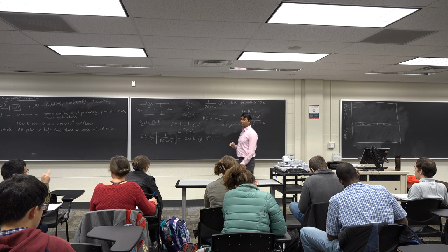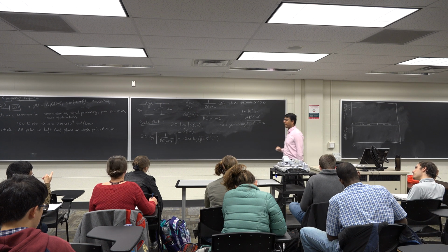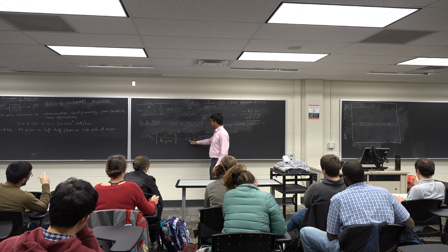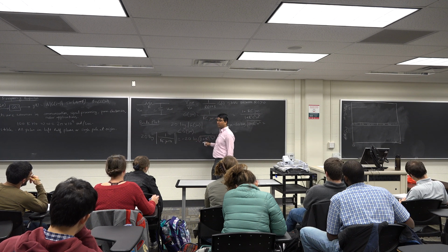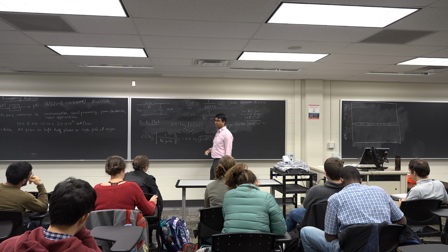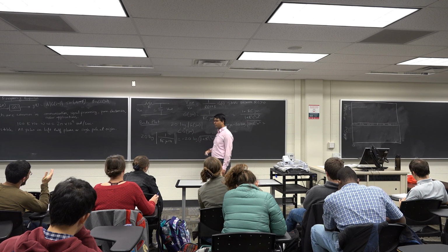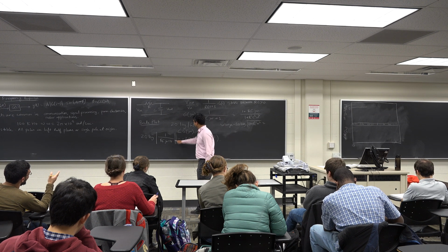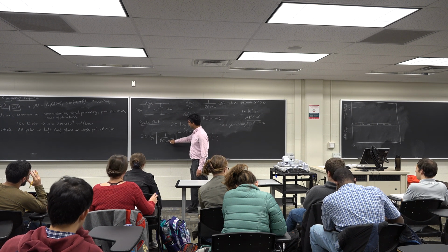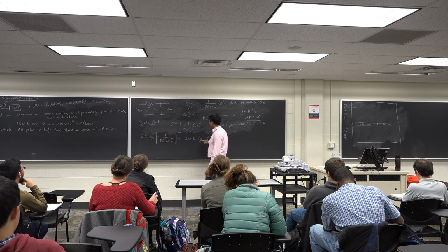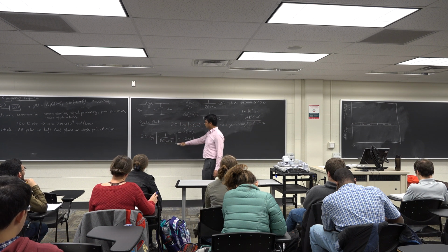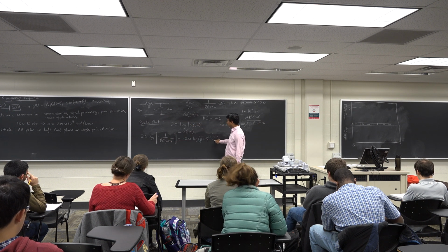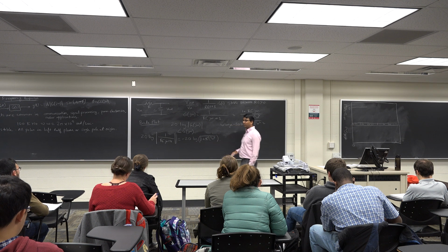I had a question about the math. Isn't that supposed to be 20 log of RC j omega plus 1? Yes, and then the minus sign in the front because it's in the denominator. I just don't know how you jump from that to the square. From this to this? Yeah. Okay, because it's in the denominator, I can put a minus sign in front and take this to the numerator. And then what's the absolute value of 1 plus RC j omega? Oh, it's the square root of 1 plus R squared C squared omega squared.